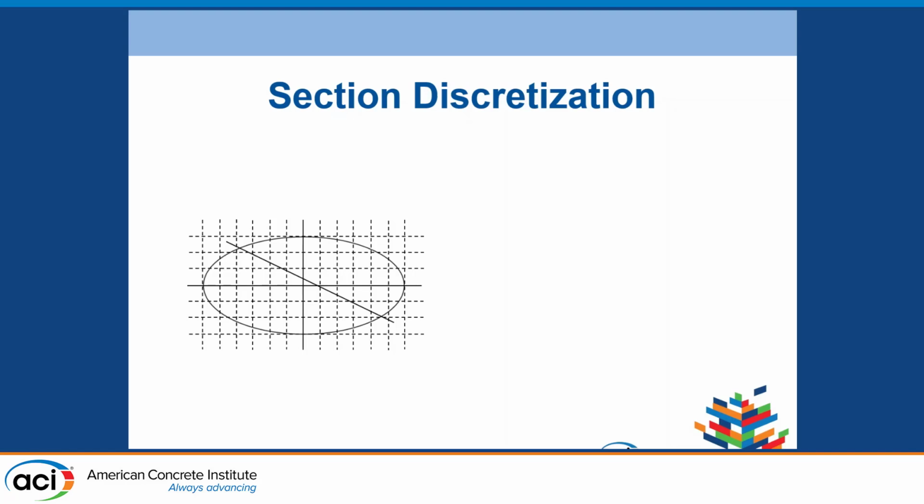Now, a solution for that, we can actually shift the grids a little bit and make an irregular mesh where we would have only rectangular and triangular elements, and we get rid of all the other elements. And this way, it does simplify the problem for us, but then we still have the issue of execution time. We need sufficiently large elements in order to get an accurate solution, and it was taking a bit of time to execute when we employed it into the software.